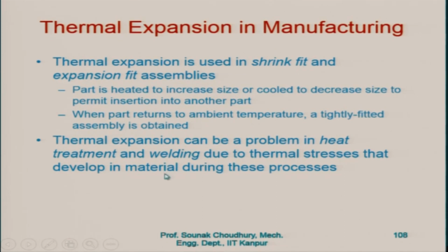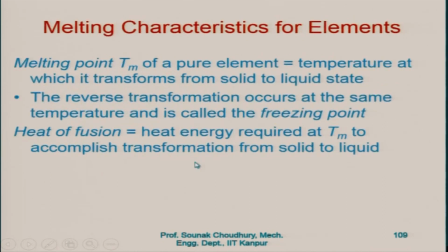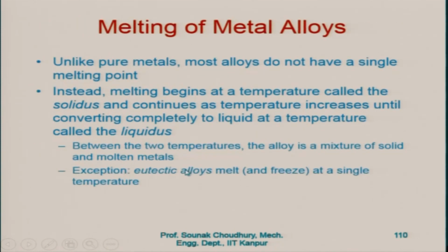We will discuss fits and tolerances in more detail. A part is heated to increase its size or cooled to decrease its size. This permits insertion into another part. The melting point of a pure element is the temperature at which it transforms from solid to liquid state. This is just a reminder. Heat of fusion is the heat energy required at the melting temperature to accomplish the transformation from solid to liquid.